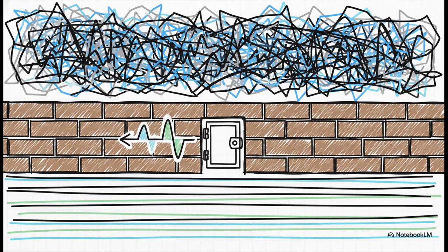When data is flying down that serial shift register at megahertz speeds, the register bits are constantly flipping, right? 1, 0, 1, 1, 0. If the active system logic was directly connected to those shifting bits, the chip outputs would be thrashing wildly, potentially causing physical damage or complete system crashes. So JTAG utilizes a separate parallel shadow register.